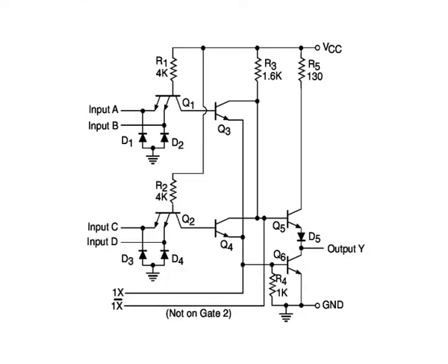The number of emitters in each of the input transistors determines the number of literals in each of the minimum terms in the output sum of products Boolean expression. How wide the gate is going to be is decided by the number of input transistors, which also equals the number of drive splitter transistors.